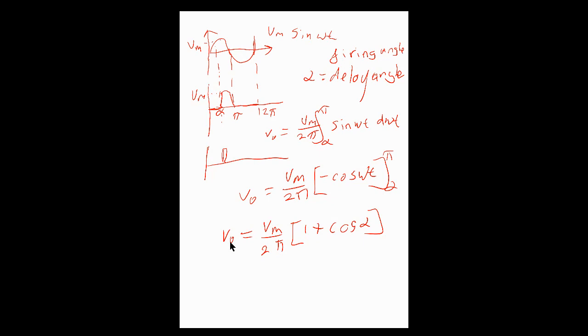Of course, we'd have studied in electrical machines and drives different ways that you can control the speed of a DC motor. You have the field control, you have the armature control, all these different methods. So by connecting this SCR across, it could be the field or the armature, you'll be able to vary the speed of your motor.